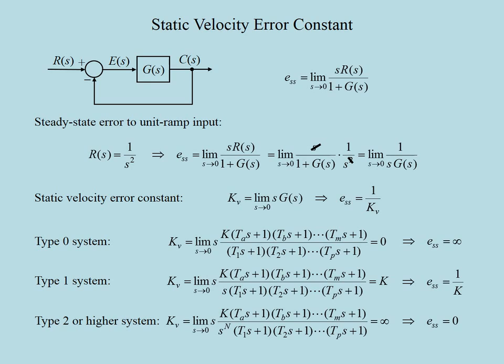It is also interesting to note that the static error constants are named as if implying servo systems with position outputs. Namely, if the output is position, a unit step input would be a command to the system to change its position to a new constant, whereas a ramp input would be applied if the system is to be run under constant velocity. Nevertheless, the use of error constants is by no means limited to position control systems. They are used for any physical quantity of output.